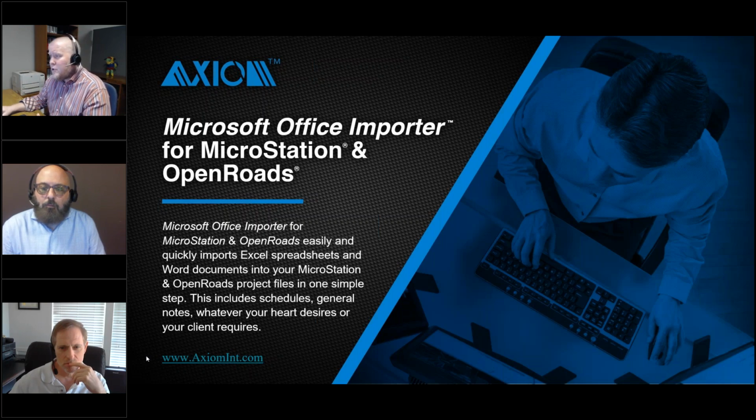Thanks to Robert for that question. Next one is from Matt. I'm going to guess, because there's like an 80% chance that Matt is in either Texas or maybe Florida, that the question is, any problems with the Leroy font? No problems at all. There's a lot of use of our software in Texas and elsewhere, and we work with any font that MicroStation can handle. So Office Importer, TrueType fonts, MicroStation RSC fonts, or if you're in AutoCAD and using AutoCAD fonts, that's totally okay too.